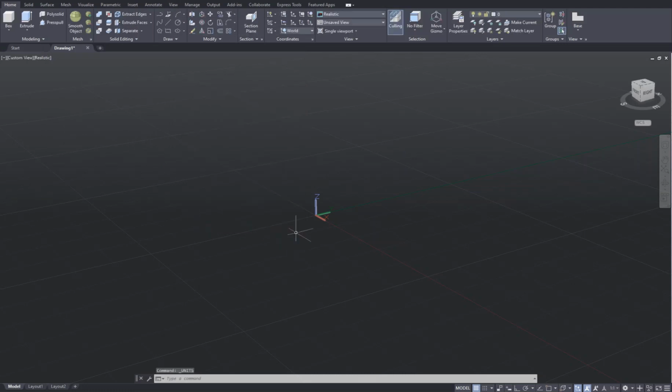Second, limits is important. I'm typing limits. Lower left is basically the lower left hand corner, 0, 0. It's offered by AutoCAD inside the default chevron marks 0, 0. Accept that by pressing the enter key, and the upper right hand corner is about 12 inches by 9 inches. This is also fine. Enter.